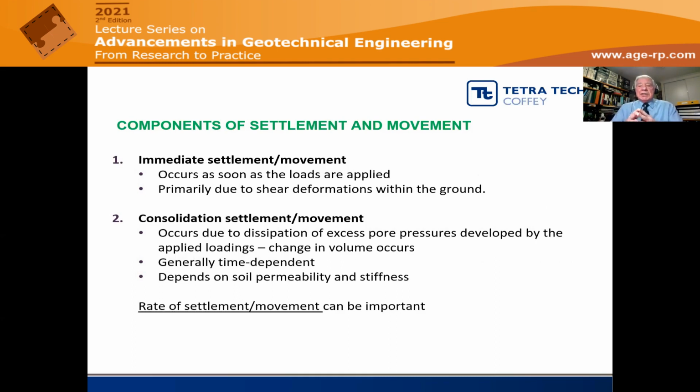Coming on to serviceability, we have to recognize that there are various components of settlement and movement that we may need to consider. The first is immediate settlement or movement, which occurs as soon as the loads are applied to the foundation, and is generally due to shear deformations within the ground. The second component is consolidation movement, which occurs because the loading of the soil causes excess pore pressures, and you get a gradual dissipation of those excess pore pressures as the water escapes, and a change in volume.